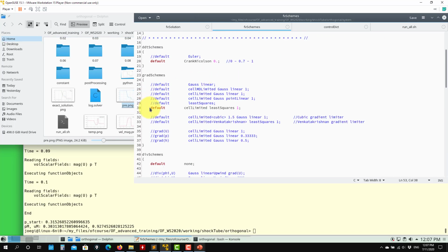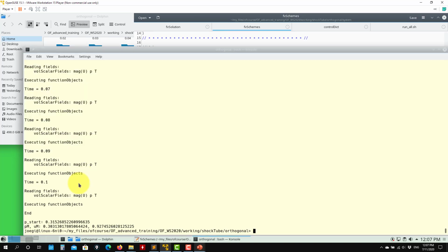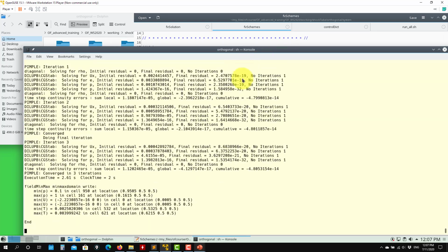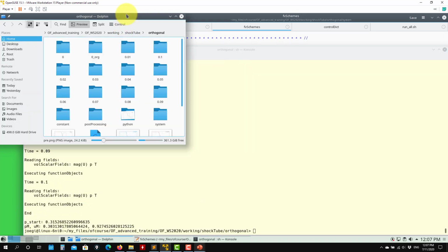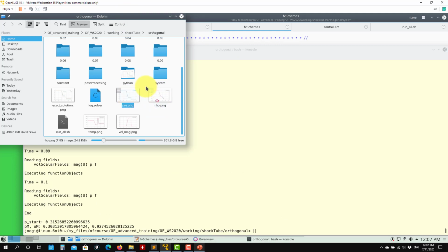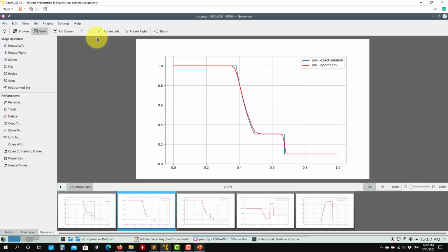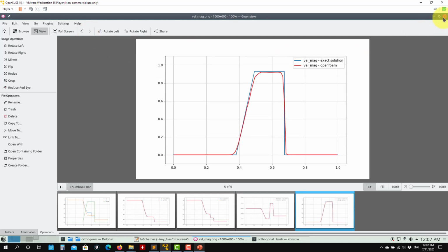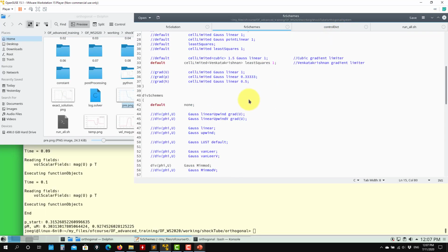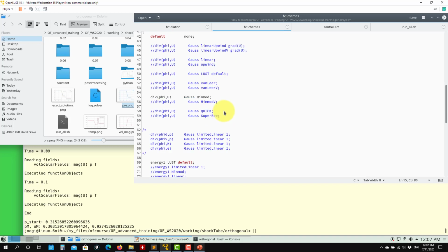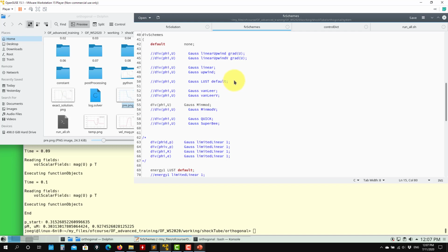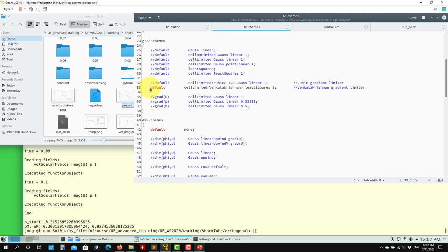And if I go back now to this one, now let me use this one. So one of the things at the beginning I mentioned is that there are many discretization schemes in OpenFOAM available. So generally speaking, don't get lost in that. Remember that you just need to know upwind, linear, a good TVD, and linear upwind, and probably a bounded linear, like limited linear. That is the only thing that you need.